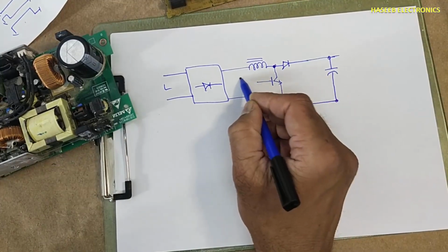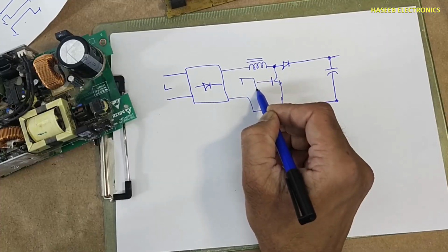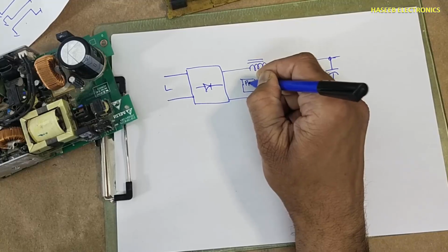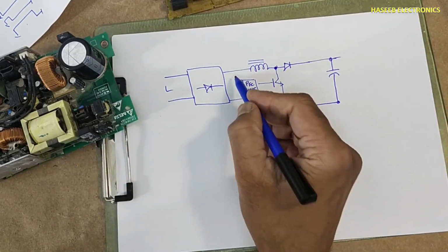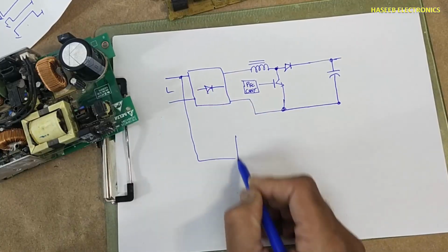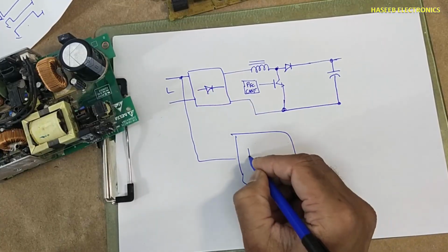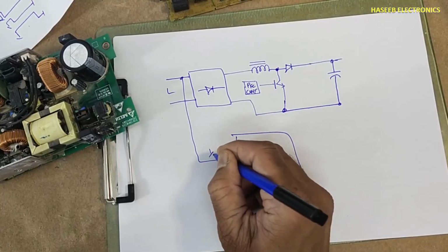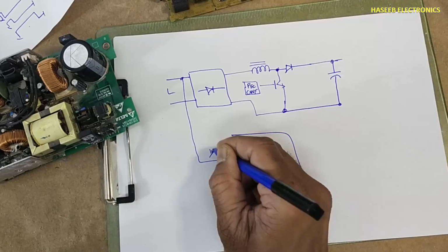It is being controlled by PFC controller. PFC controller IC will sense the voltage present at this line, input voltage.